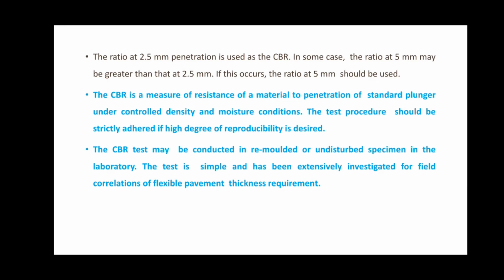The standard load values, obtained from the average of a large number of tests on crushed stone, are 1370 and 2055 kg respectively at 2.5 and 5 mm penetration.